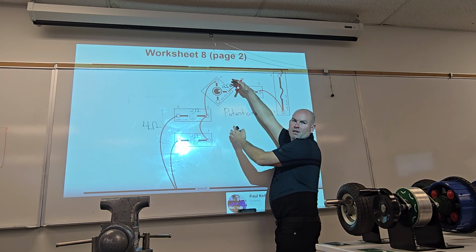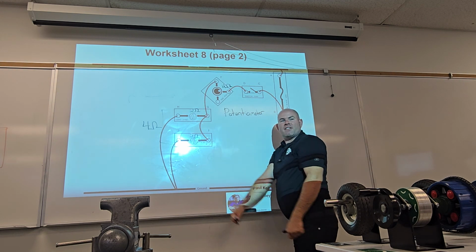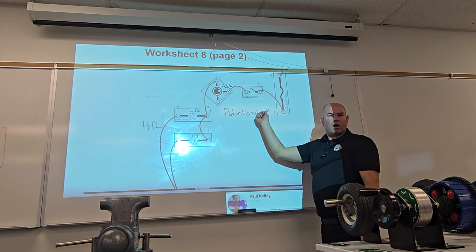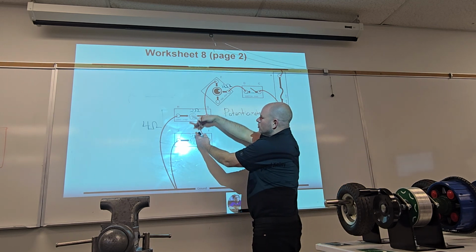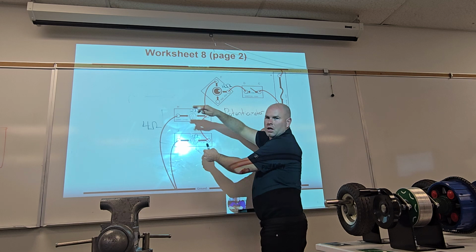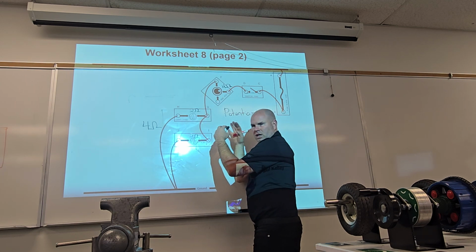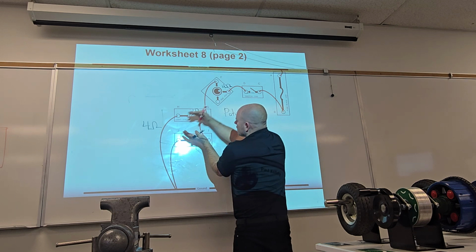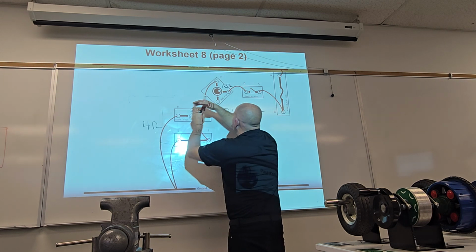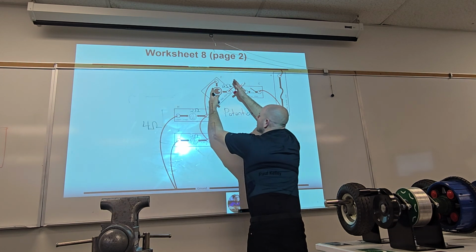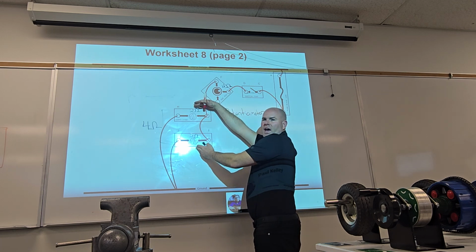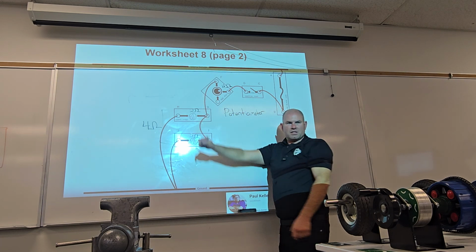So if this is like money, it's half. The available voltage was 12, so you get half, and these two both get half, which is kind of weird. But if you look at just the parallel part and think of these as one load because they're combined 4, and this is combined 4, you take half and leave these two half. That sort of makes sense?